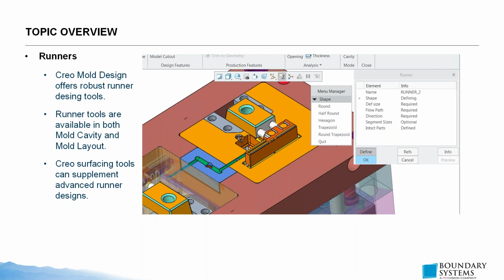Again, the hot runner example that I just spoke to is arguably some exception here, clearly. But in most cases, we're going to have a scenario where runners in a conventional sense intersect more than the cavity assembly. It makes a lot of sense to me to hang that stuff up in the skeleton model or whatever the case may be, or at minimum, be hanging those features in their definition inside of the mold layout